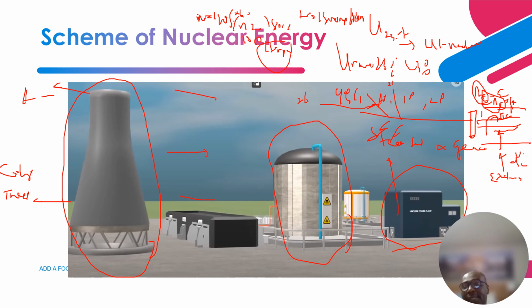Then the stator magnetic field will also rotate until it achieves a synchronous rotation. At the time that both magnetic fields achieve the same synchronous rotation, the same revolutions per minute, that is when they lock in place, right? So that is what they call synchronous speed. At that time, let's say about 80% of the voltage has been built up. Then the remaining 20%, it continues rotating at that synchronous speed until the rated terminal voltage is achieved.